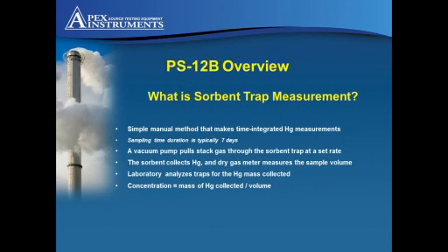What is sorbent trap measurement? Well, Mick has already touched on what sorbent trap monitoring is about. Continuous repetitive in-stack sampling using paired sorbent traps with subsequent analysis of the time-integrated samples. However, the tester should have a knowledge and understanding of stack sampling methods including 30B.